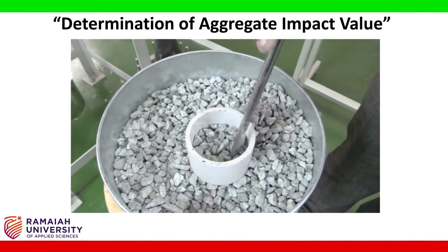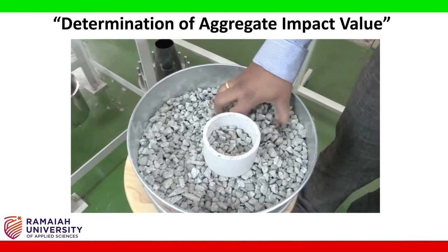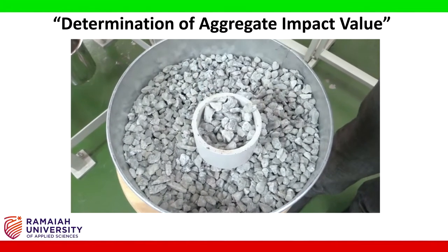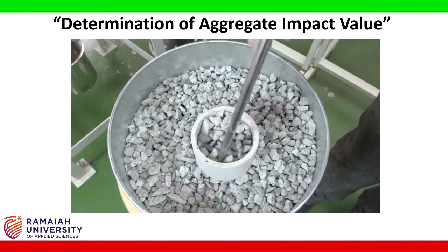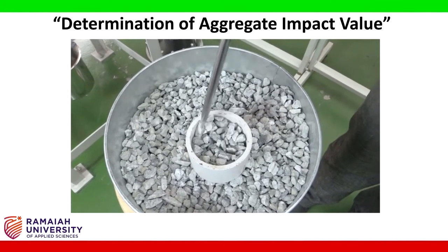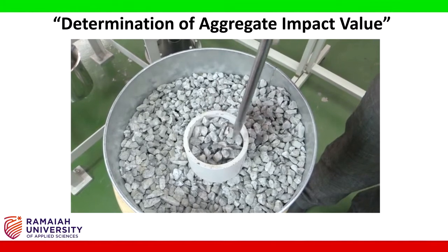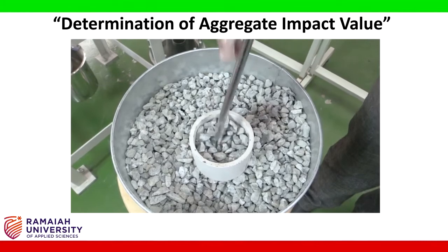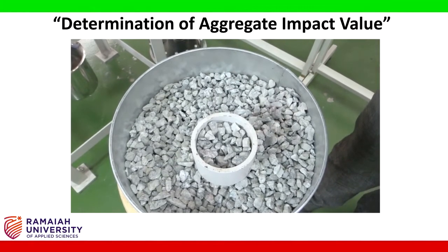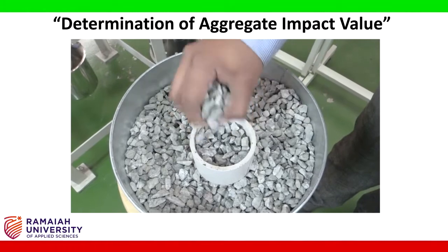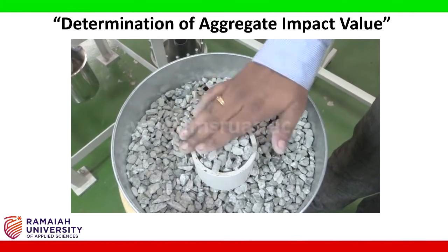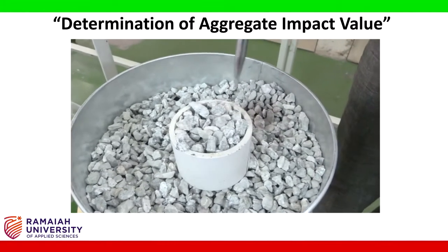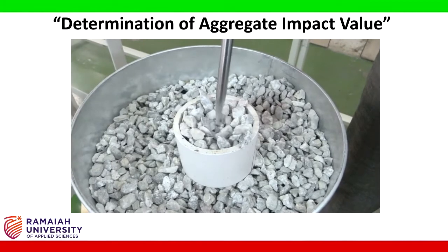This is the first layer. I'm placing the second and third layer. At last, I am placing the last layer, and I start giving 25 tampings to this layer.